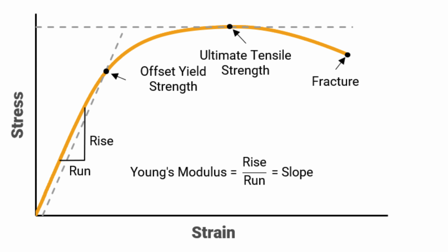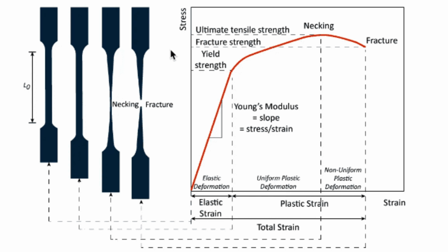In the early, low-strain portion of the curve, many materials obey Hooke's law to a reasonable approximation, so that stress is proportional to strain, with the constant of proportionality being the modulus of elasticity, or Young's modulus. As strain is increased, many materials eventually deviate from this linear proportionality, the point of departure being termed the proportional limit. This nonlinearity is usually associated with stress-induced plastic flow in the specimen.